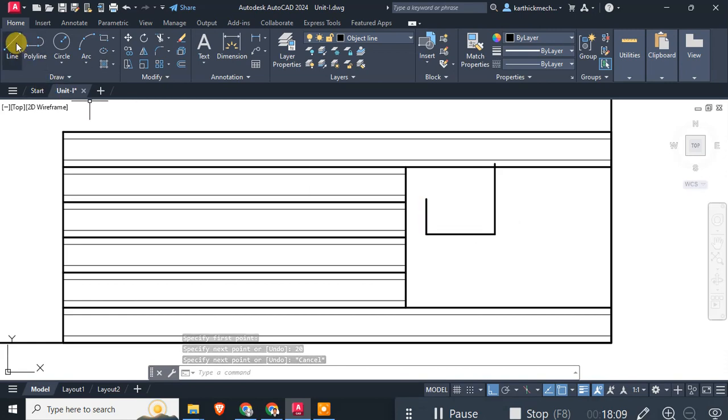Now I am going to create the midpoint. See, if I drag over this line, a midpoint icon, this triangle, has been enabled. So I have to create a midpoint, and I am going to draw a line. Okay, now I am going to move this particular 20 mm line here at the midpoint. The large line's midpoint has to coincide with this midpoint.